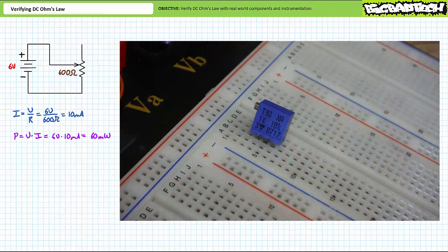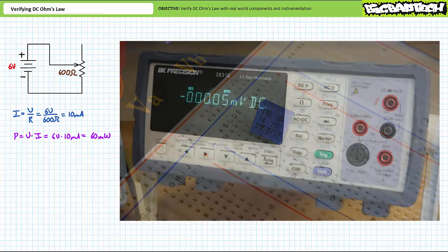Install the potentiometer on the protoboard such that the adjustable middle terminal is landed on node 5A through E, and the bottom terminal is landed on node 6A through E immediately below it. The one and only path from node 5A through E to 6A through E is through a portion of the potentiometer currently set to 600 ohms.